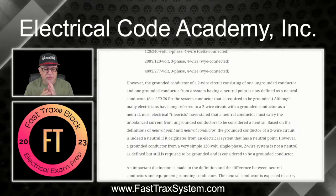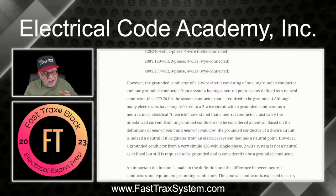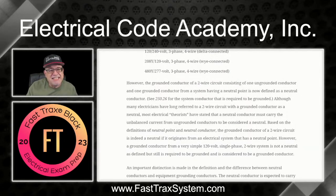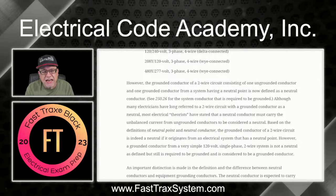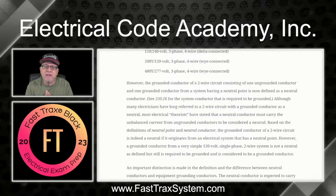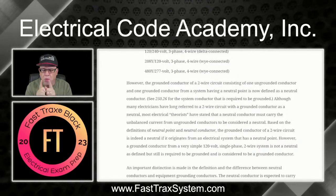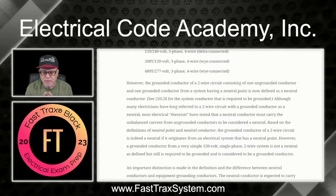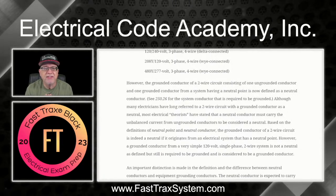Now, discussion. I'm going to get a little bit into the difference between theorists and what the NEC says. In 2008, when they came up with the definition of neutral and added neutral point, it started to take the theorists, who said, wait a minute, if I have a black and a white in a non-metallic sheath cable, the white wire, if we understand the neutral, is to carry the imbalanced load.